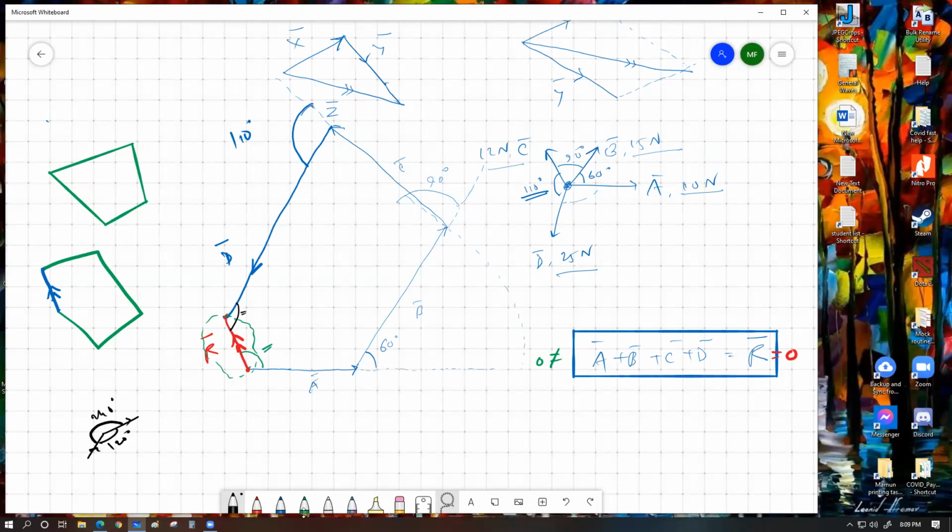or polygon rule, that if you are trying to draw multiple forces one after another, the resultant is always obtained in the opposite sequence of the component vectors. So it means that the resultant will be aimed from the starting point of the first vector of your diagram towards the end point of your last vector. That's how we get the resultant from triangle rule drawing.